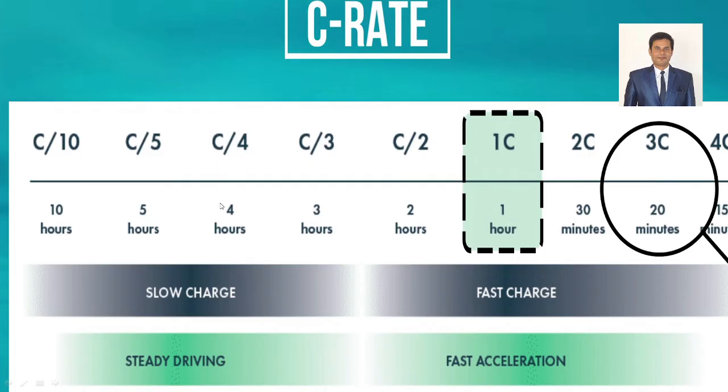During that time, please also focus on the temperature of the batteries, because the temperature has to be maintained very constant, right? It should not be increased or decreased. If the nominal temperature is around 25 to 26 degrees centigrade, then please try to maintain that temperature during charging and discharging, right? Temperature should not increase.